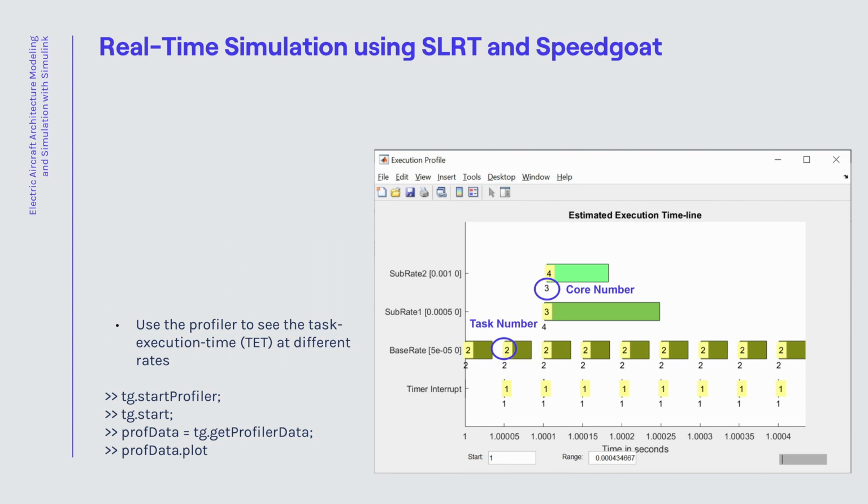Second, the thermal system takes around 2 base rates to execute, and the Brayton cycle gas turbines take around 3 base rates to execute. This tells us that we would be unable to simulate the full system in real time if we didn't split the sample times across the different model sections, and if we were unable to use slower sample rates for the thermal systems and Brayton cycle gas turbines.